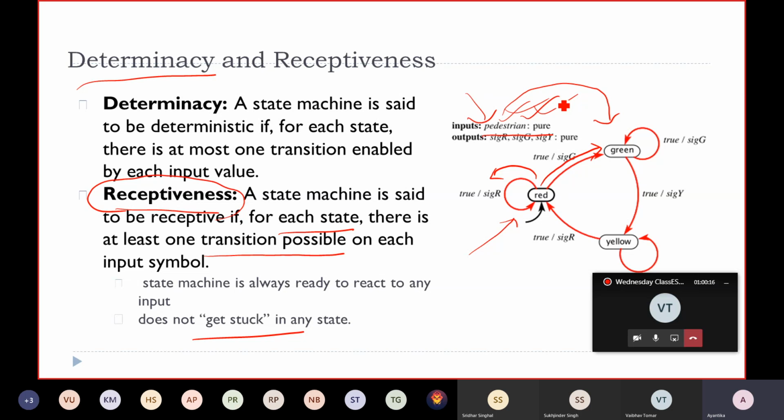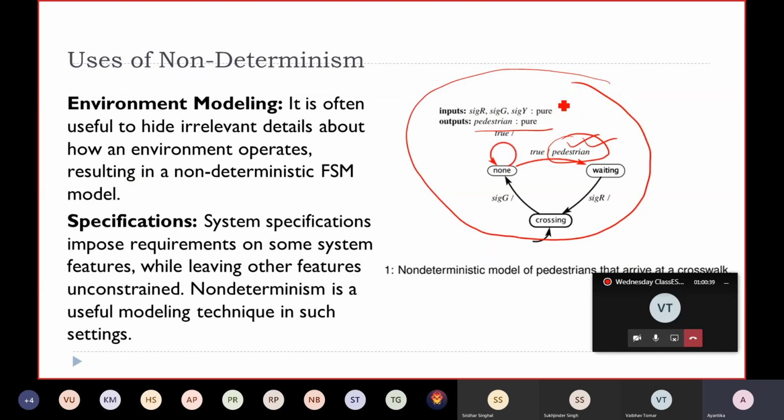So when we design a complex system, we do not think about one single FSM. We should always think about communicating FSMs, which communicate through inputs and control signals. If we think about the pedestrian in the crosswalk, I was just mentioning what their states can be.